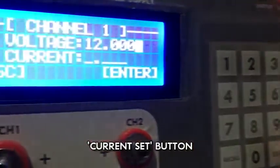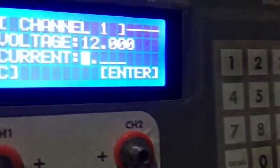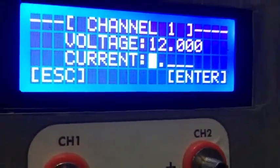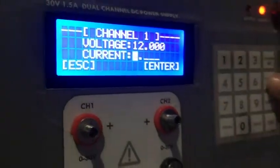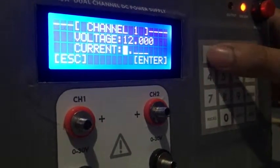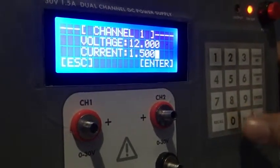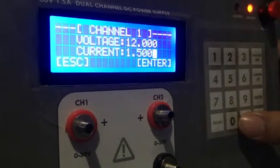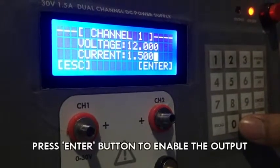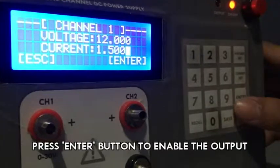Next, I will set the current. I will press the current set button. We can see that the cursor moved down to the current and is prompting us to enter a value. I would like to set the current to 1.5 amperes. I will press 1, 5, 0, 0. In order to apply this setting and enable the output, we need to press the enter button for OK.